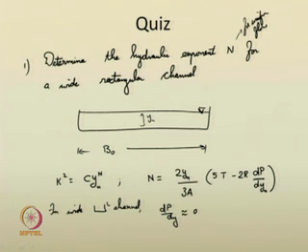Therefore, you just substitute it in your N. You know A is equal to b0 y_n, T is equal to b0. Substitute the quantities, delete appropriate terms, you will get N equal to 10 by 3, that is equal to 3.33. Fine. So, this is the hydraulic exponent for uniform flow in a wide rectangular channel.